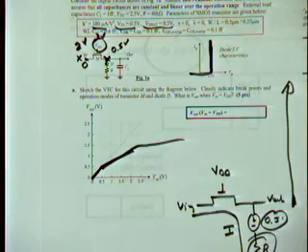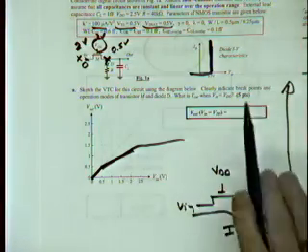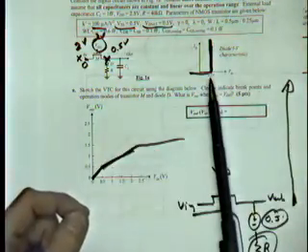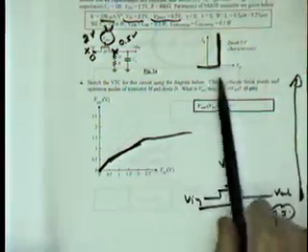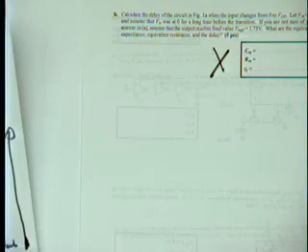Yes? What about the capacitor? Capacitor doesn't matter. This is a voltage transfer characteristic, so it's a static characteristic. I'm not looking at transients. I apply an input voltage, and I can wait long enough, the output voltage will appear. The capacitor is only necessary for part number 2, where we say compute the propagation delay of this network.